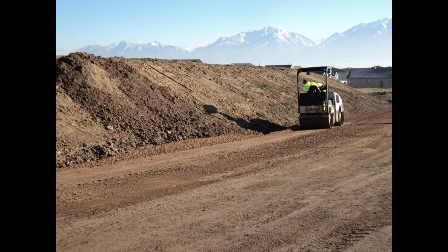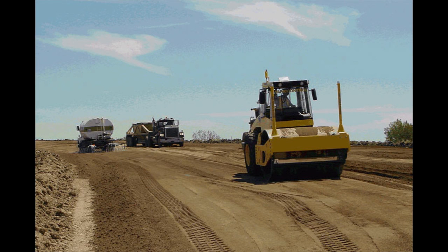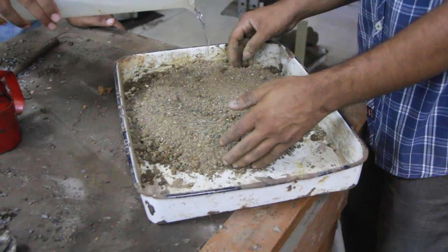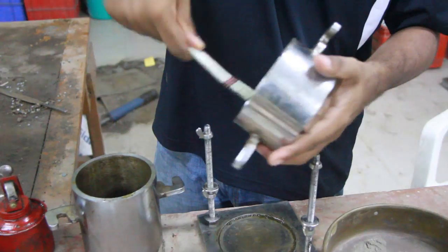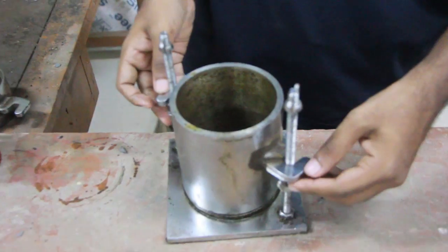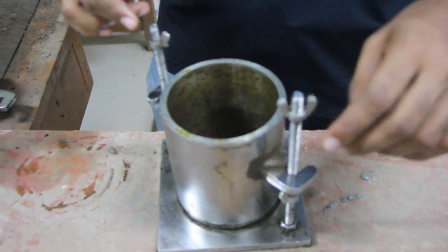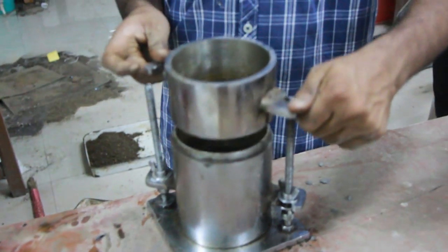Well, there is an optimum water content, OMC, which corresponds to the maximum density of the soil. This is what we found out by the Proctor compaction test. The test procedure consists of adding a known quantity of water to a soil mass and then compacting it into a standard cylindrical mold. Yes, everything including compacting effort is standardized by the codes.